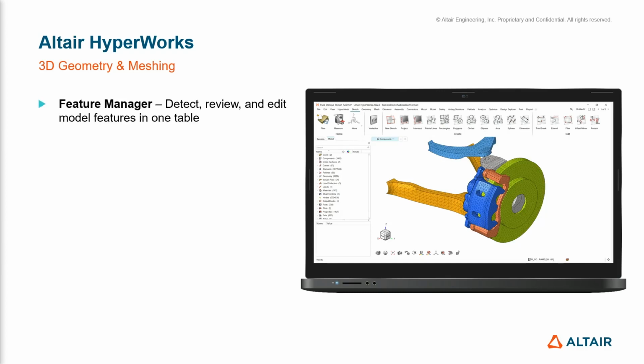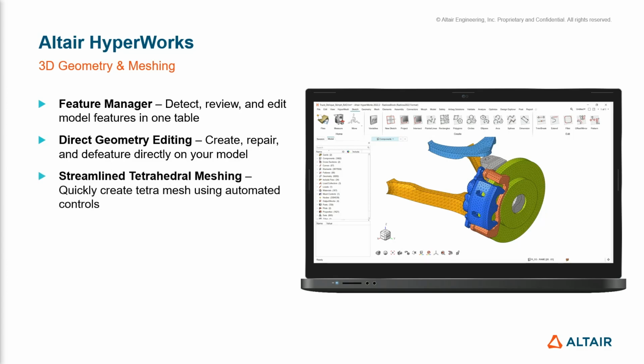First off, we looked at the feature manager and how this allows us to detect, review and edit model features in one simple to use table. Next up, we looked at direct geometry editing and how we can create, repair and defeature directly on our models within the modeling window. We then had a look at the tetrahedral meshing workflows and how we can quickly create tetra mesh with optionally using automated controls to speed up the process further.